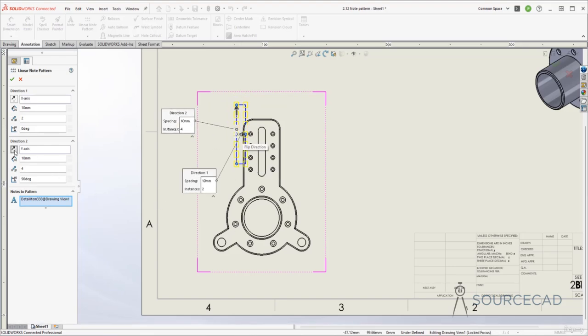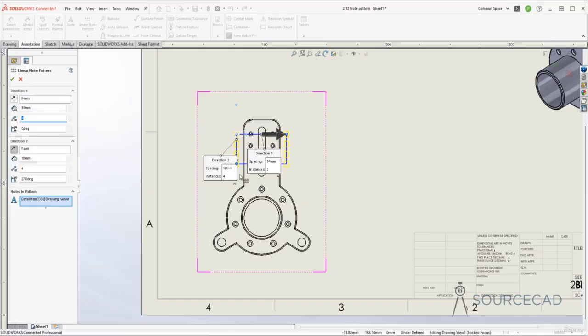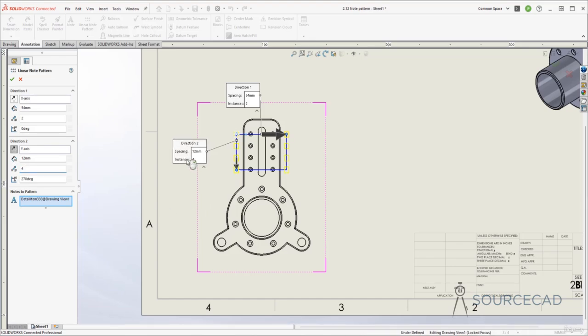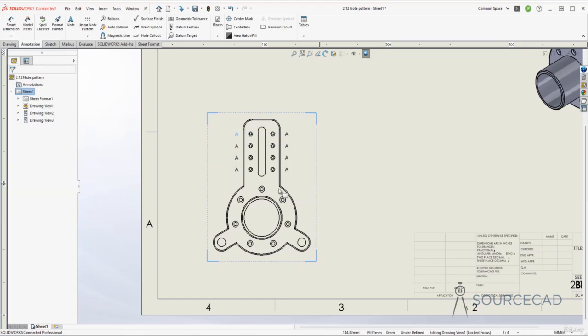So I'll just click here to reverse the direction and then I'll change the gap along X. The gap value is right here. So I'll just click here and well, 50 looks about good, but maybe I'll just make it 54. Well, that's better. So with 54, this is the gap, and now we need to fix this distance. So this is also about right, but maybe we can fix it with, well, 12 units. So 12 units looks good. So with that, now everything is right where it should be. Just click OK, and we have the node pattern.